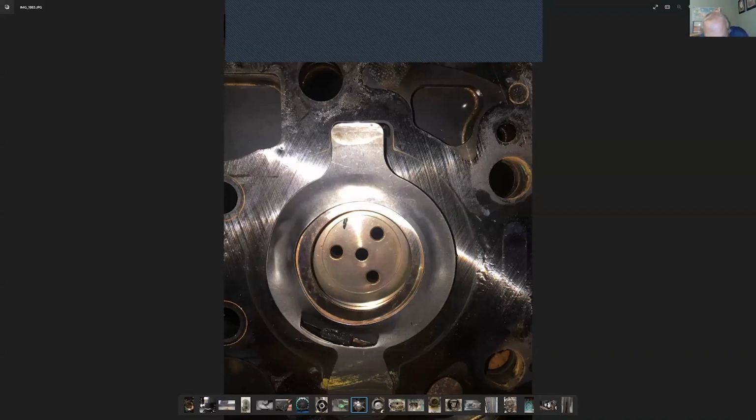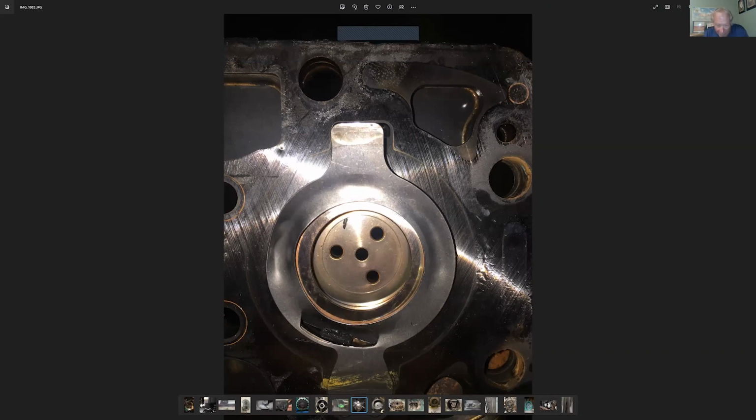Oh, there's a little damage to our Delta reed there, it looks like. This thing took what I call a liquid slug. And most of the time that is refrigerant, but we have seen some of these where all of them get busted, and it can be related back to what they call a hydraulic or an oil slug. That's a nice pick there, Trev. That's for sure.